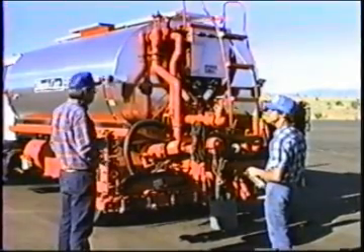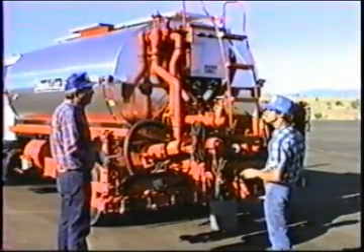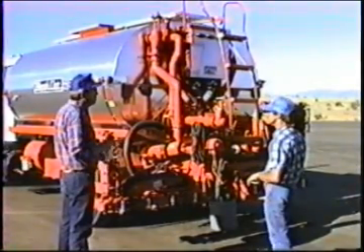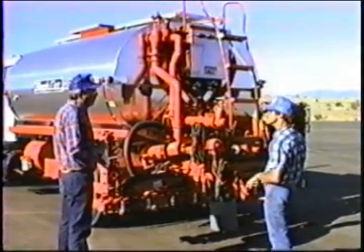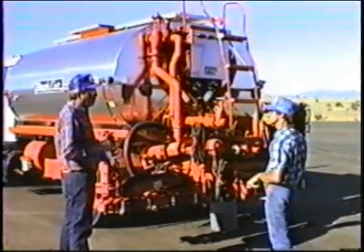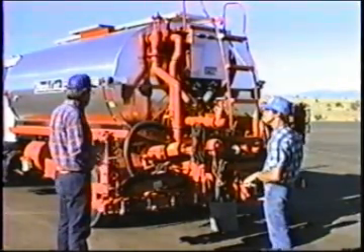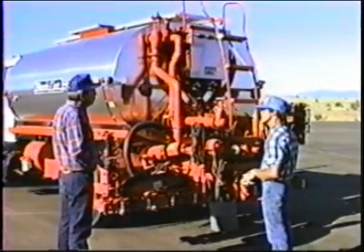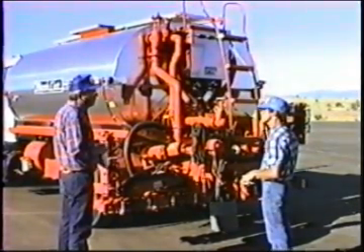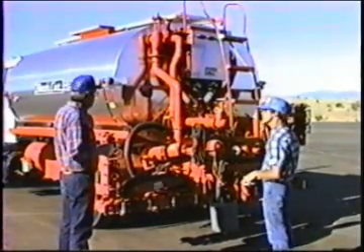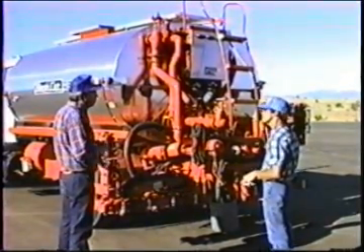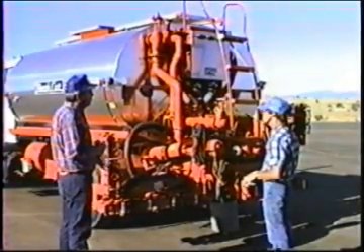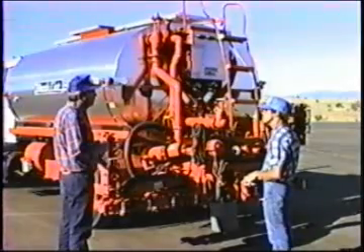If you go from cold material to hot material, you have to take some very definite precautions. A lot of places won't even let you load the truck if it was wet the day before. They talk about wet and not wet. If we had emulsified asphalt in this yesterday and we went to a tank farm and we wanted to load hot asphalt, material that's 300 or 400 degrees, anything over the 212, they may not let us. If you understand what you're doing, you can load it just fine.